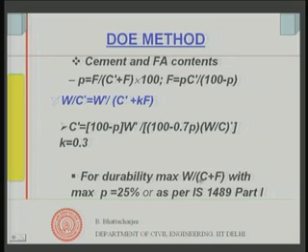So at the moment there is not much benefit in using P more than 25, because in the durability calculation this will not give you an advantage, although it might give you other advantages, heat of hydration and many others. For durability it is restricted by the maximum percentage allowable in Portland pozzolana cement code, that is IS 1489 part 1.